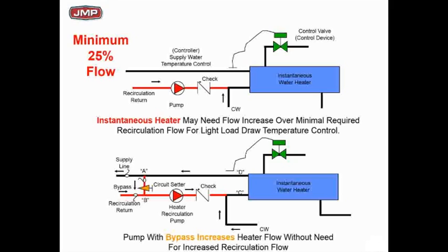What's that steam control valve going to do? It's still sensing temperature, right? And it says it's cold. It's going to open wide open with 1.5 GPM of cold water as the only load. So your load is what? 1.5%. Your load is 1.5%, and you're going to dump 100% capacity on it.